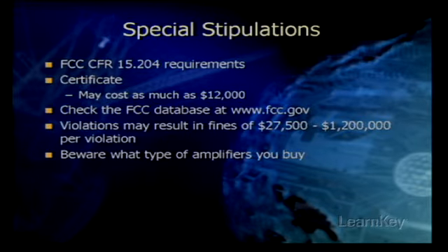The other thing that's very important is the FCC CFR 15.203 says that installers are responsible to make sure that intentional radiators are used with authorized antennas. Antennas may be made such that they can be repaired, but not attached to non-certified matching intentional radiators. This is very important. Well, probably one of the most common questions that should be addressed regarding this special stipulation of 15.204 is that one manufacturer's antennas may not be used with another manufacturer's intentional radiator without FCC certification as a system.